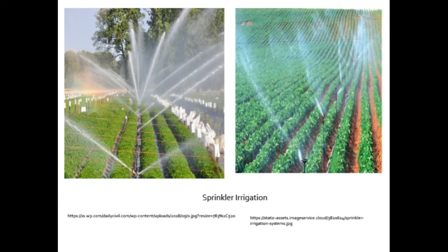Surface ditches and prior land preparation are not necessary for sprinkler irrigation. Also, the flexible pipes and fittings can be transported to remote areas easily. Sprinkling is suitable for sandy soils or any other soils and topographic conditions where surface irrigation is insufficient or expensive, or where erosion of soil may be particularly hazardous.